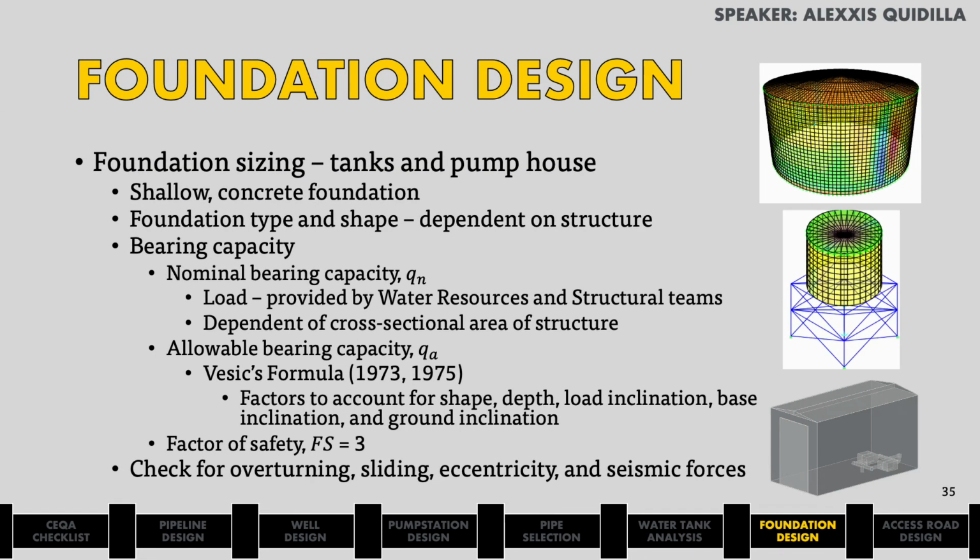My name is Alexis, and I'll be summarizing how our geotechnical team was able to design and size the foundations for our 3 structures: the storage tank, mining site tank, and the pump house, which are located on the right side of the slide. Since the bedrock is very deep at our project location, and the aforementioned geotechnical investigation and boring logs do not indicate unstable soil layers, shallow foundations made out of concrete were deemed appropriate.